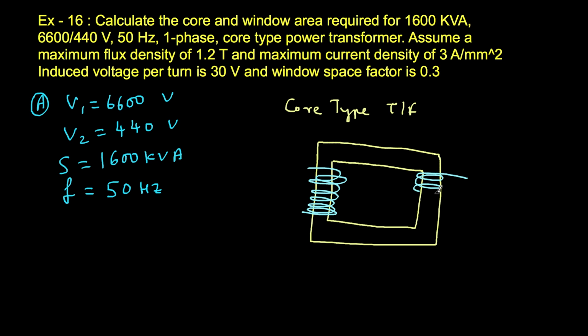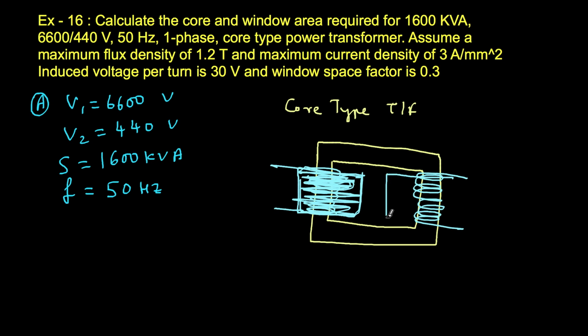Although in the diagram I am showing separately the primary winding and secondary winding, both windings may actually be together. In fact, to draw it more accurately, this wire might be a little bit thicker, so it might actually take this much area. So this is the entire winding like this. And here also it takes some more area. So when you are designing the transformer, it is always beneficial to not have this extra place here.